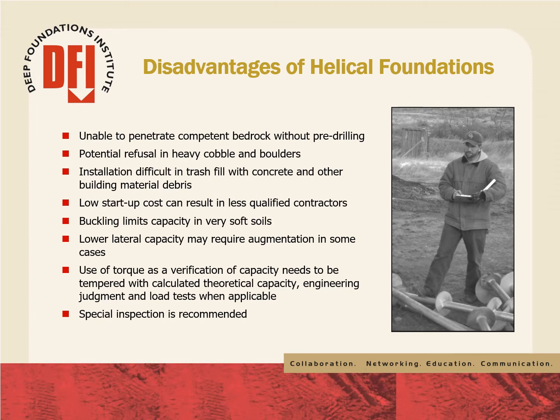This slide lists several of the possible disadvantages of helical piles. Major ones are unable to penetrate competent bedrock without pre-drilling, potential refusal in heavy cobble and boulders, installation difficult in trash fill with concrete and other building material debris.